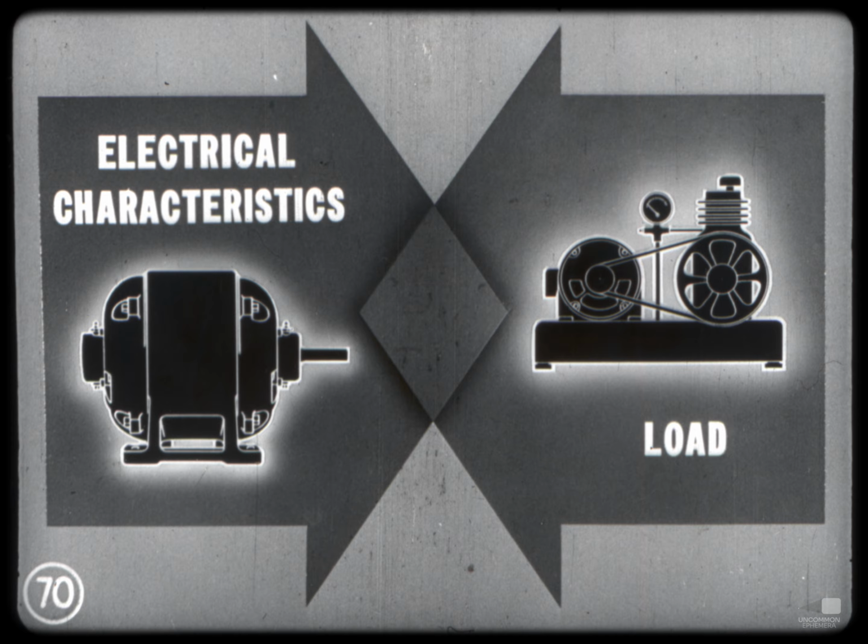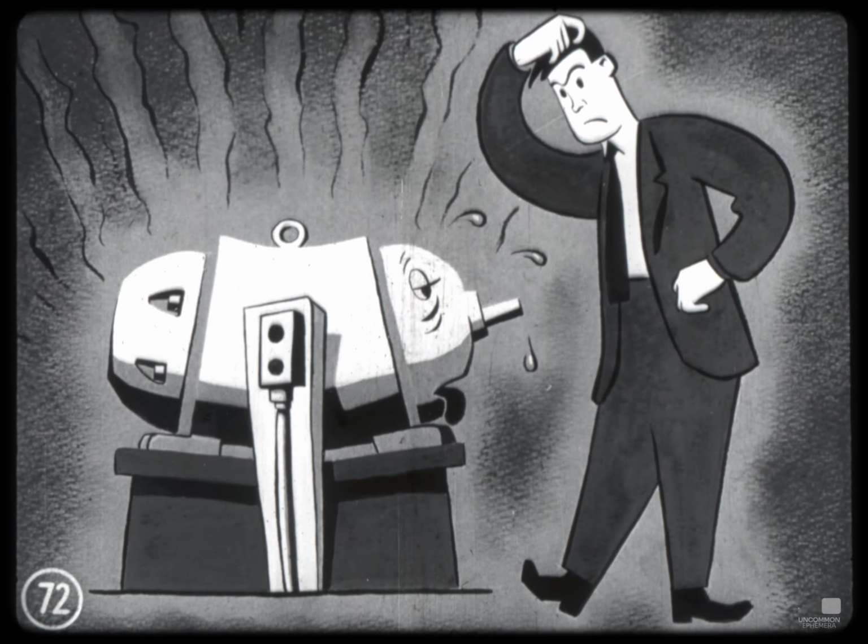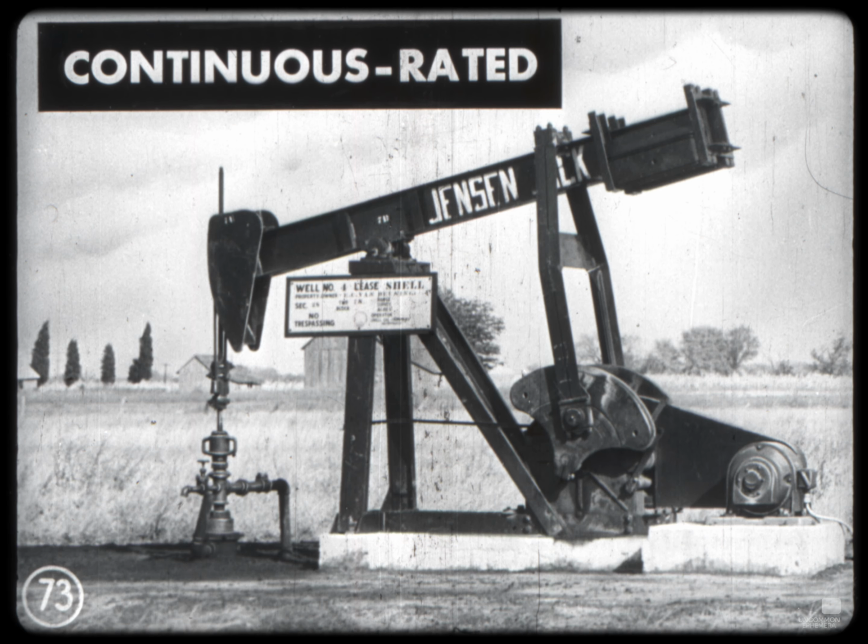In other words, the motor should provide the torque needed to start, accelerate, and pull the load during the machine's cycle of operation. In addition, the motor rating should be sufficient to avoid overheating during its required period of duty. Here's how this point is judged. Whenever a machine operates at full load for more than an hour, it should be continuous rated, designed so that heating resulting from normal load won't cause the temperature of any part of the motor to exceed its rated temperature rise as shown on the nameplate.